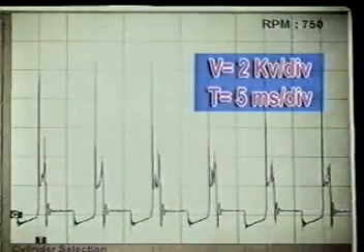Okay, let's go to a problem vehicle and do a scope check, and let's see what the ignition scope is trying to tell us on this vehicle. We want to prove to you how important it is to scope check a secondary circuit in the event the car comes in for a tune-up with some mileage on it. In other words, we're looking at a high mileage vehicle that's a little bit rough, with a choppy idle. Car came in for a tune-up.